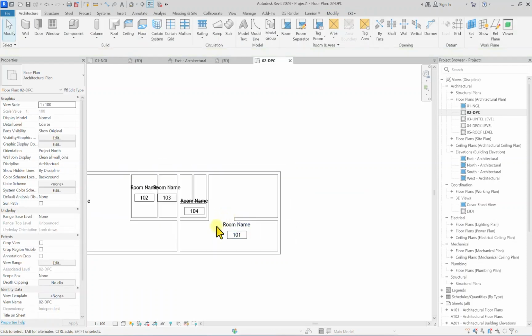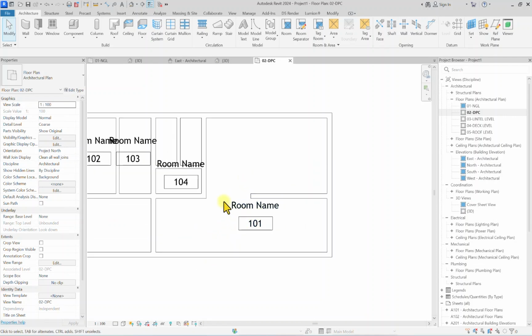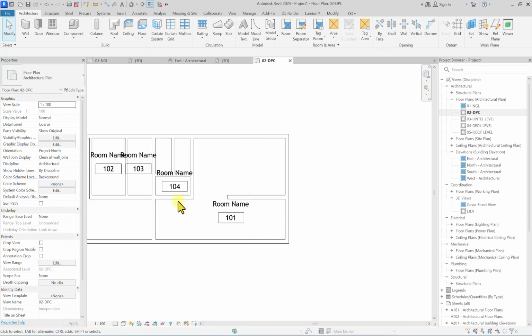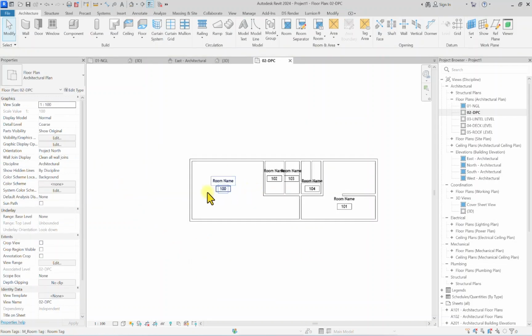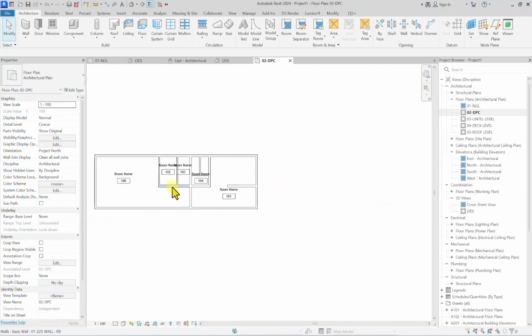So we have a problem here. There are about 3 distinctive spaces we want in this place. We want the stairway here. We also want this waiting area and we want the reception. But the room is selecting this as one space, and the reason is that we didn't demarcate it, because rooms recognize walls as demarcation tools. But there's a way we can tweak it.